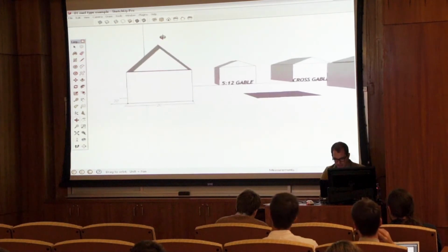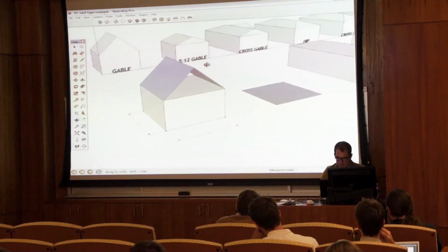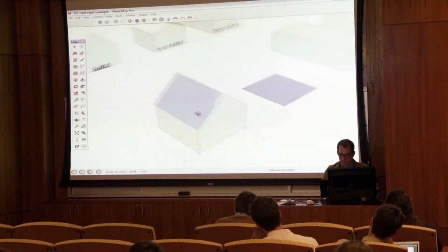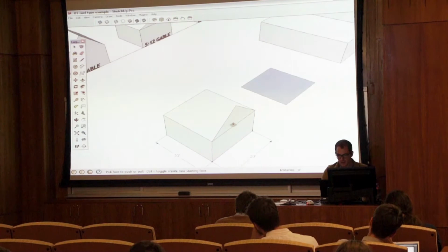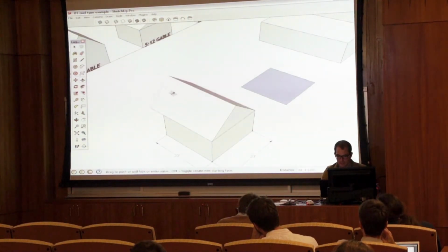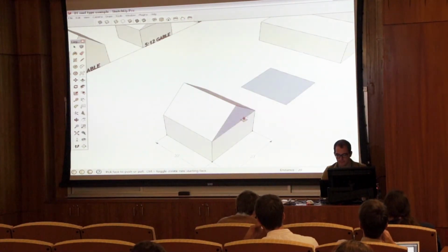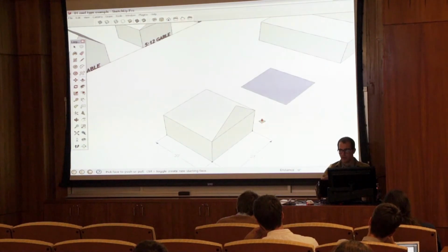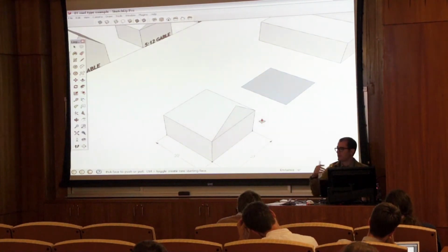Now you'll see there's a slight glitch with SketchUp. It actually pushed this and inverted the whole face. But you can take the line tool and heal that by tracing that back in. The other way that you could fix this, see how that's pushing and it's actually not leaving the face there? As you're push-pulling, you can press the control key and it'll leave that face there and start a new extrusion from there. And that will keep that face essentially staying there.